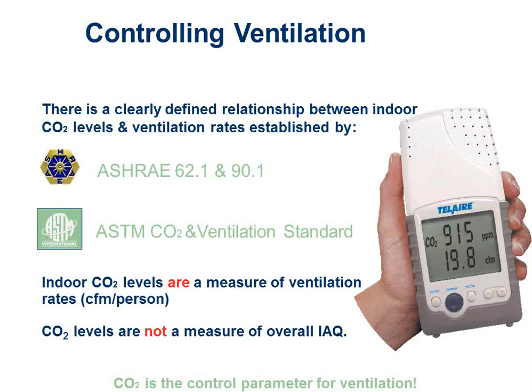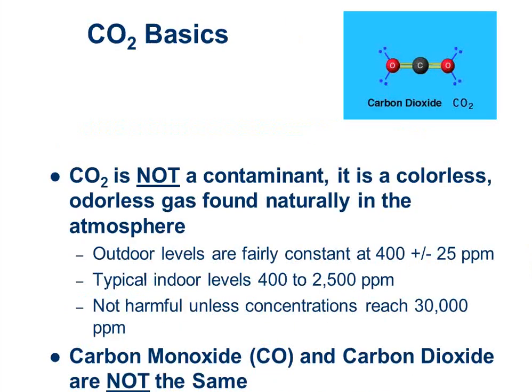So one of the things we want to understand is that CO2 levels in a space are just an indicator of how many people are actually there. It's a surrogate for counting the number of people. It has absolutely nothing to do with the actual air quality. CO2 is just one chemical that would be in the space, and it's not even a harmful one. There's plenty of other things in there that could be harmful, like VOCs, viruses, things like that we have to deal with a little bit differently, and we'll talk about that.